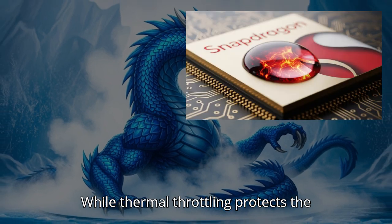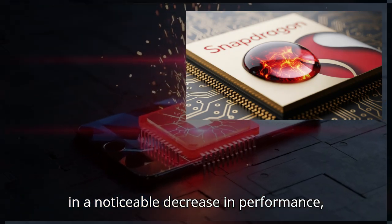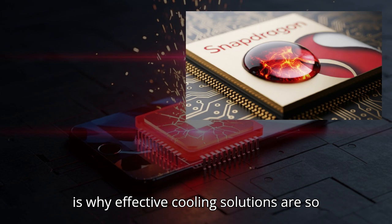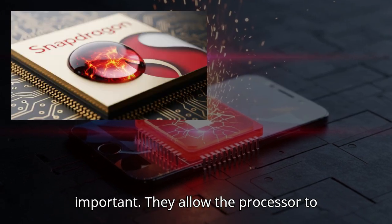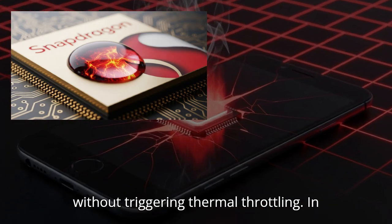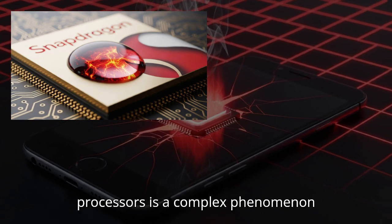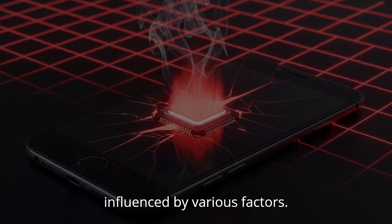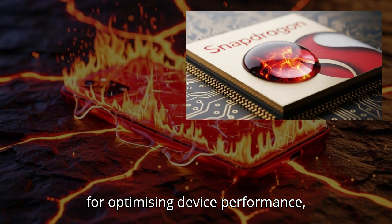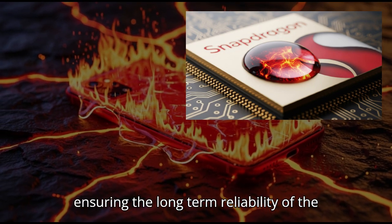While thermal throttling protects the processor from damage, it can also result in a noticeable decrease in performance, especially during demanding tasks. This is why effective cooling solutions are so important. They allow the processor to operate at higher performance levels without triggering thermal throttling. In summary, heat dissipation in Snapdragon processors is a complex phenomenon influenced by various factors. Understanding these factors is essential for optimizing device performance, preventing thermal throttling, and ensuring the long-term reliability of the processor.